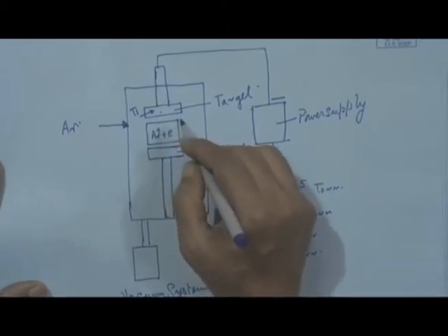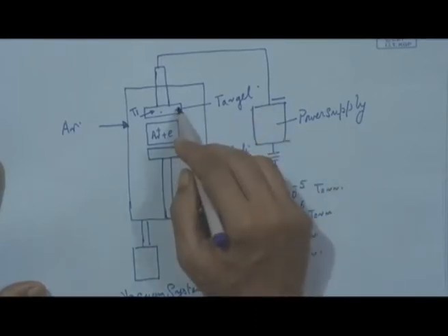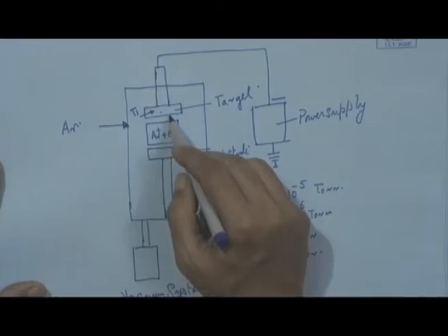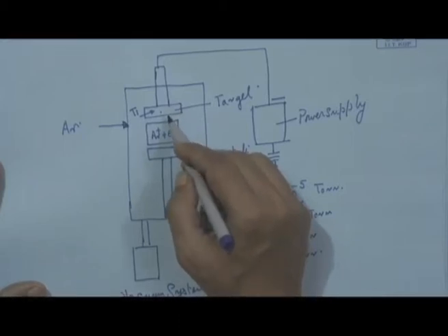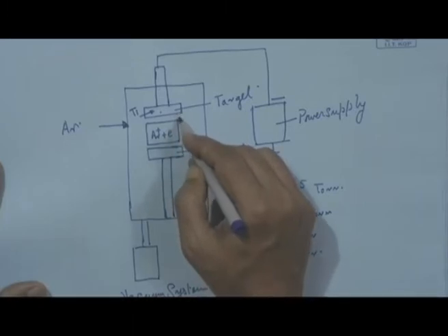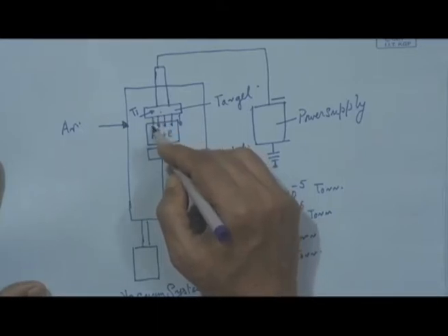this positive argon will now be accelerated towards this negatively biased surface, and will strike this surface and transfer its energy. As a result, the material will get dislodged and ejected from this surface, and it will flow in this direction like a flux of sputtered material.